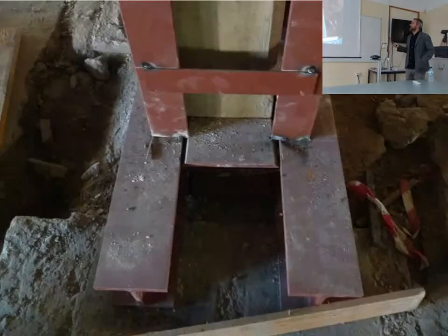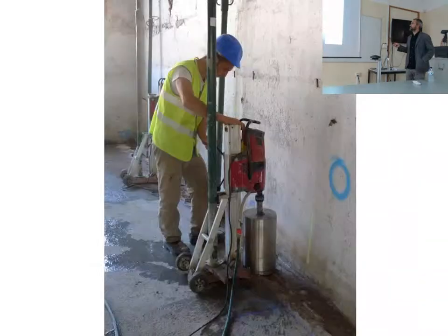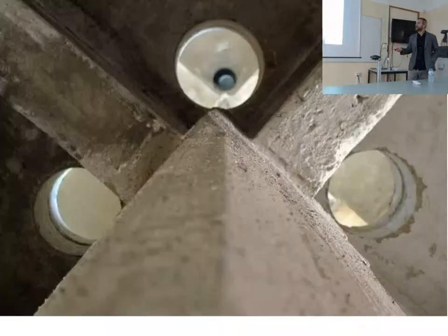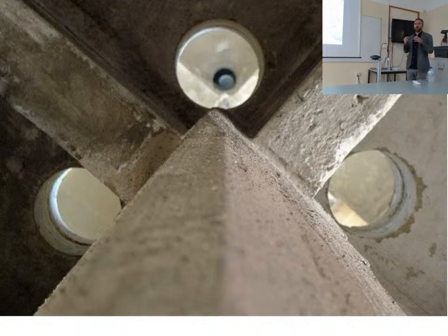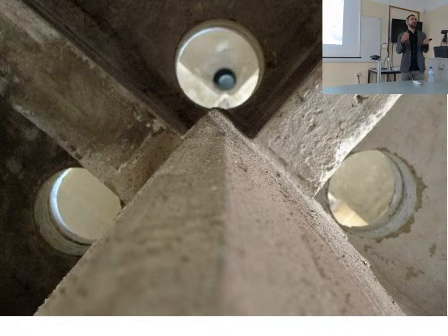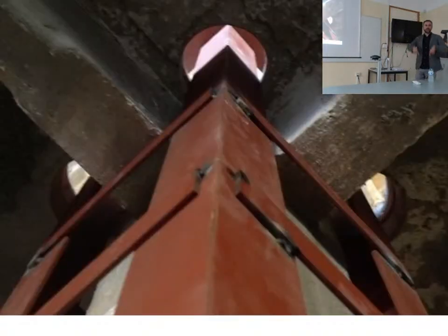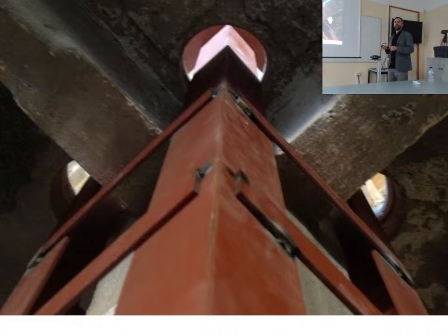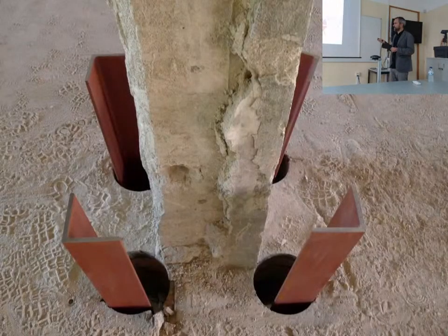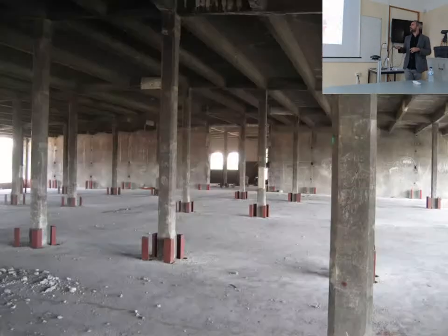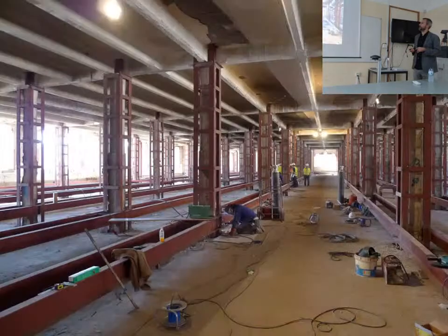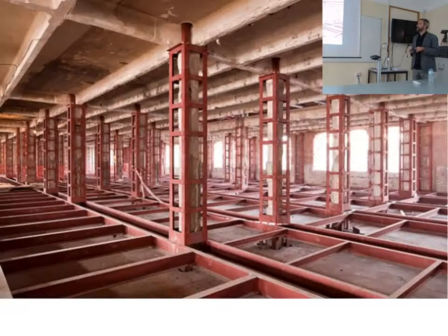And then we provide this new steel structure. We made some holes on the slabs. You see? The idea of separating the new steel structure from the concrete was also good to avoid this interference with the existing beams. And so we continued with the columns from one level to the other. You see the columns like on the next level. And then we provide some main beams and secondary joists in the other direction.